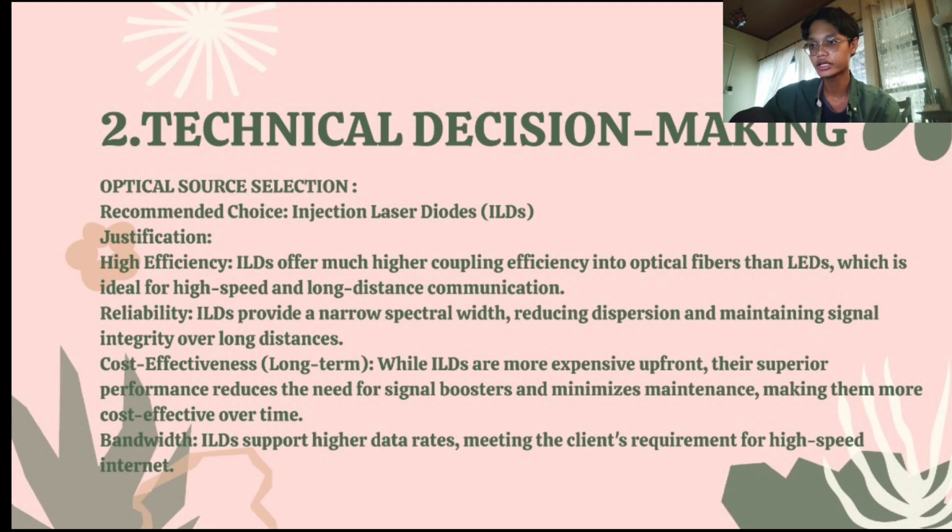ILDs offer much higher coupling efficiency into optical fibers than LEDs, which is ideal for high speed and long distance communication. It is also very reliable. ILDs provide a narrow spectral width, reducing dispersion and maintaining signal integrity over long distance. And third, it is cost effective for a long-term purpose.